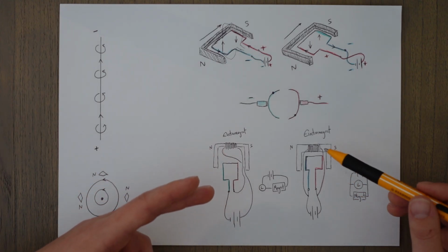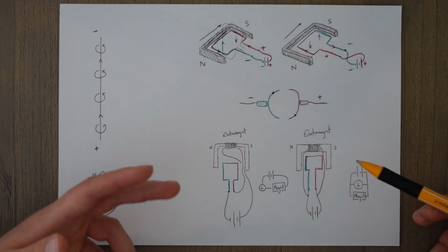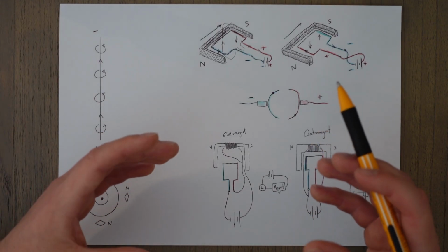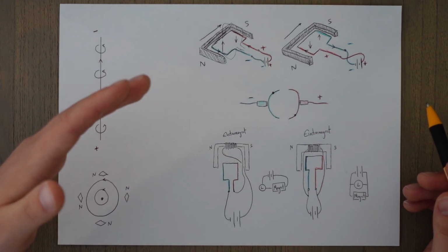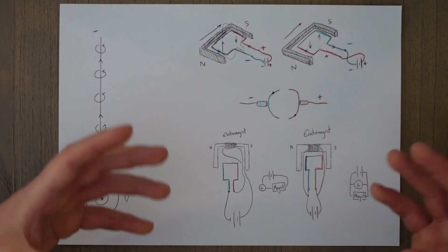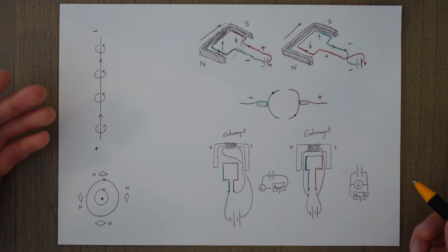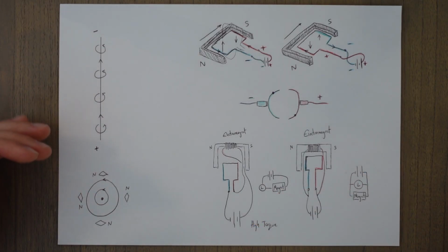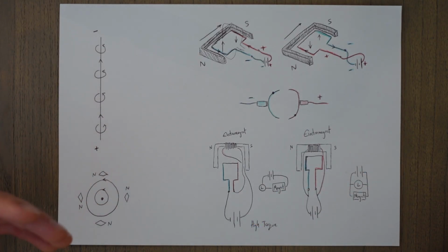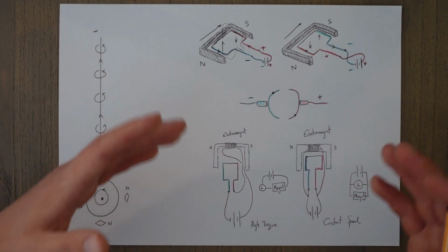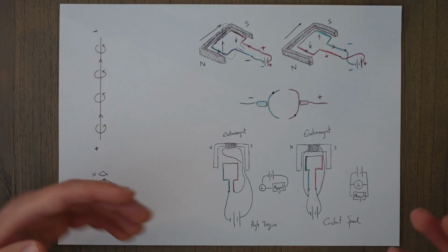You've got one that's in parallel and one that's in series, and depending on the use case, you can have a high torque or you can have a constant speed, and you would just call that a combination motor. To boil things down though, if you've got a series, expect a high torque, and if you've got a parallel wound electromagnet, expect a constant speed. Or as I say, a combination of both of them, we'd get both benefits.